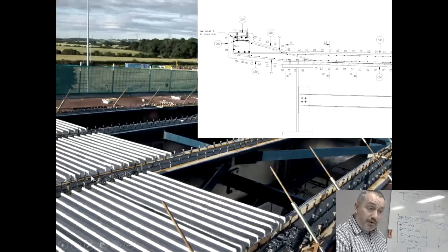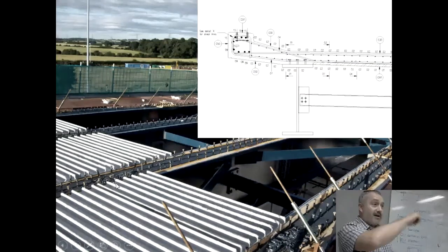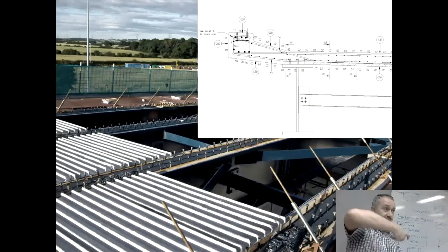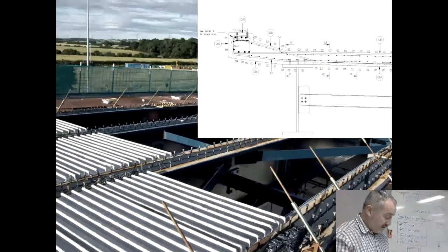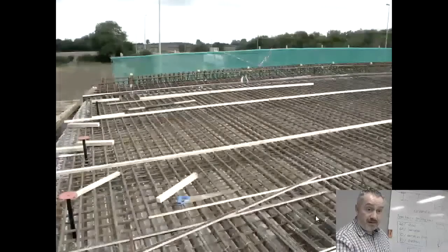Then they'll put the concrete on top. The concrete will be poured in here, and then the concrete will rest straight onto the shear studs. Are you thinking of when you've got a Wrigley tin and you can have the shear studs put through here? It's not required in terms of this design. These bars here are holding up the support that everyone's going to be working on.